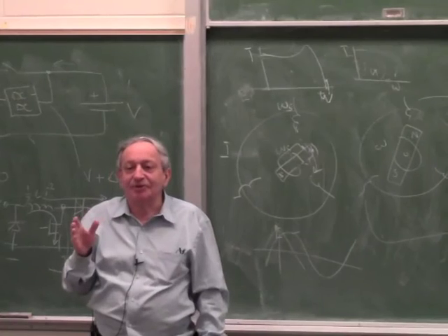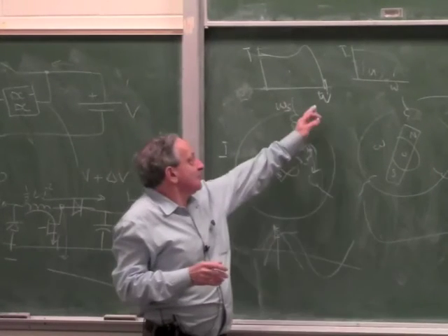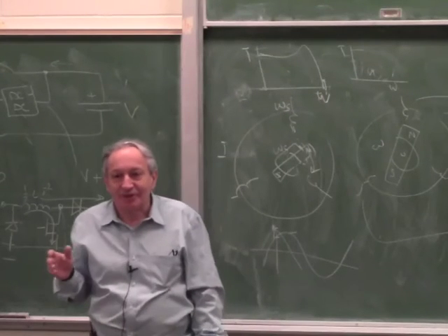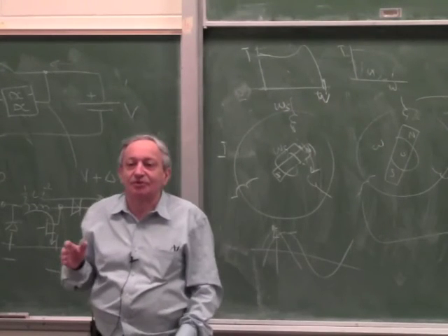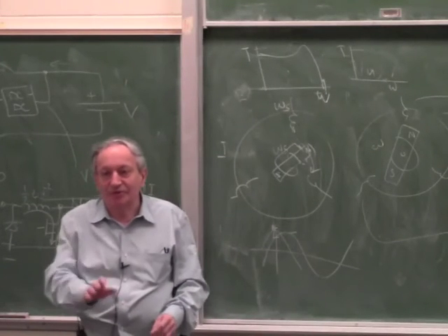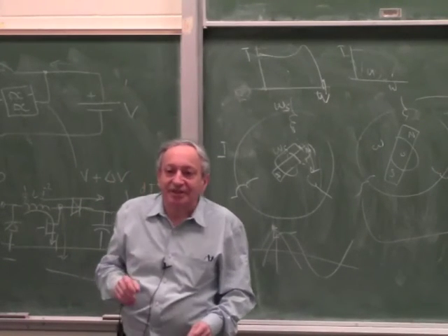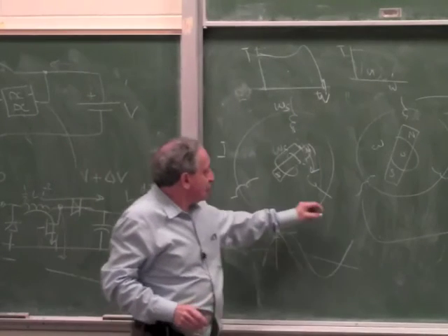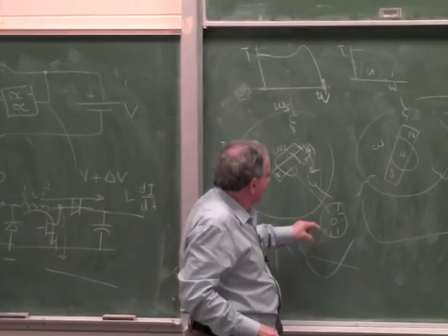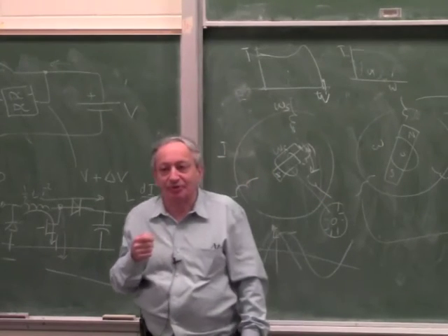And the way it works, because there is no synchronous speed in an electric car, because the car can go at any speed, is as soon as you put your foot on the brake pedal on a Tesla, or you drop the acceleration pedal, there is an encoder on the motor. There is a shaft encoder which measures the actual speed of the motor.